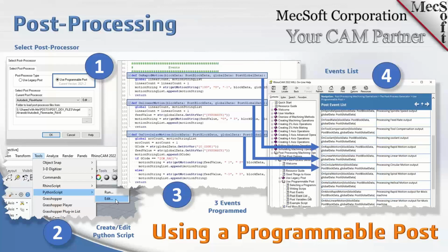If you do have experience with Python, you'll understand these steps that we're talking about here. You obviously have to have a Python script written before you set it up in your CAM plugin. We have an example Python script here. Go to your select post processor dialog. You don't want to use the legacy post option. That will be selected by default. Select the use programmable post option. That will enable you to define a Python script as your post.